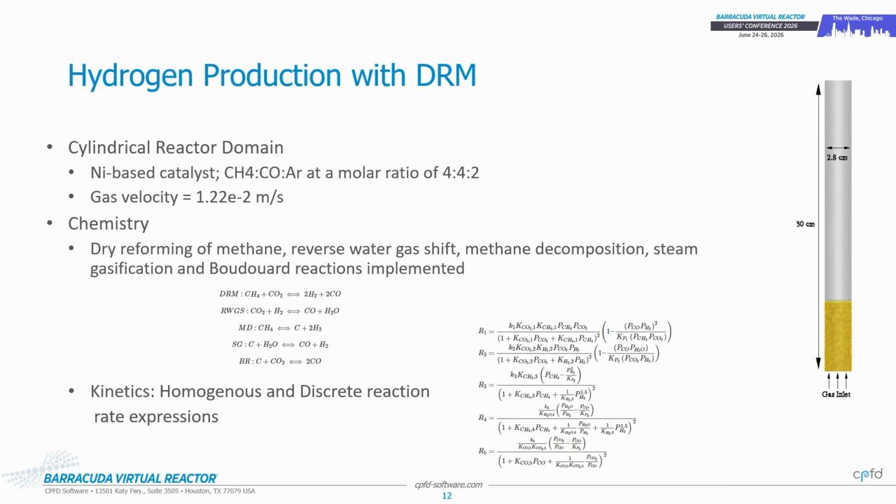So again, a very lab scale set of reactor. In this, again, the reactions change. So you have the main reaction, which is the dry reforming of methane, reacts with CO2, produces hydrogen and CO. You want to suppress your reverse water gas shift reaction in this case. That could be a function of how much catalyst you have, the temperature at which you're operating, things which you can easily test through simulations. And so that's what we end up doing, right?